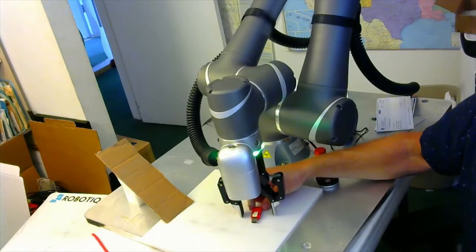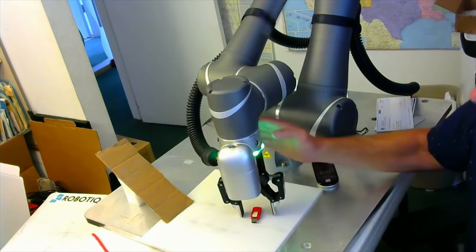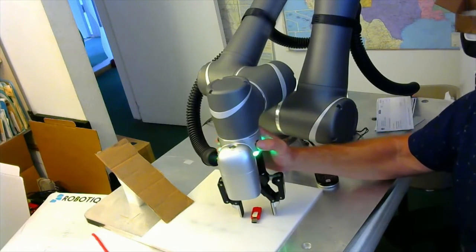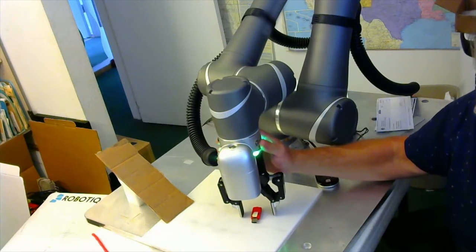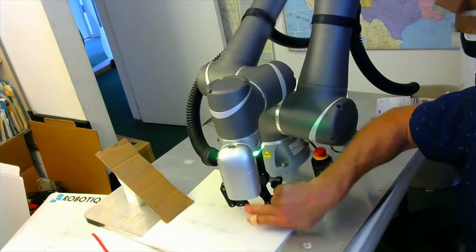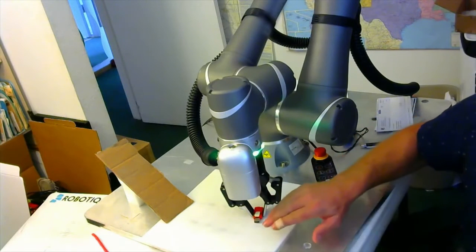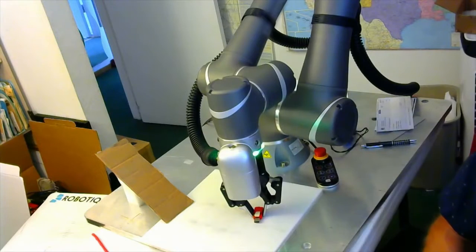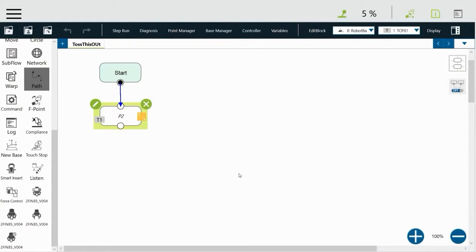That seems like it's going to be good for me, so I'll just test it out by holding the gripper button, and in a second the gripper will grip. But see how those fingers are at an angle right here? That's not the way they're supposed to be. They should be straight up and down. What happens is, as they close, they go down a little bit. So I need to go back to the program and adjust that position slightly.